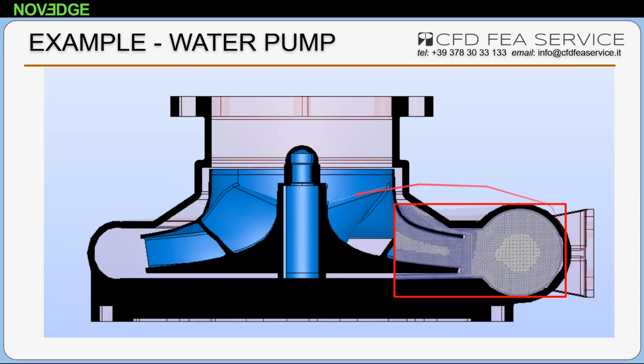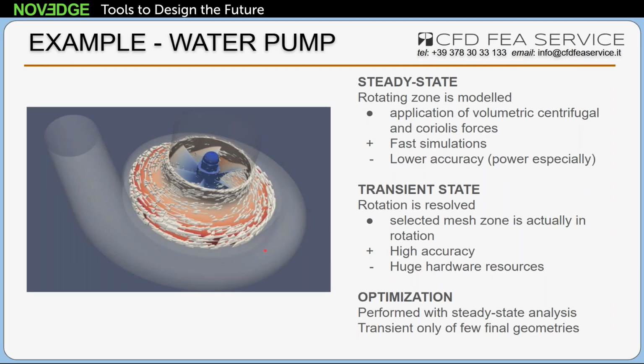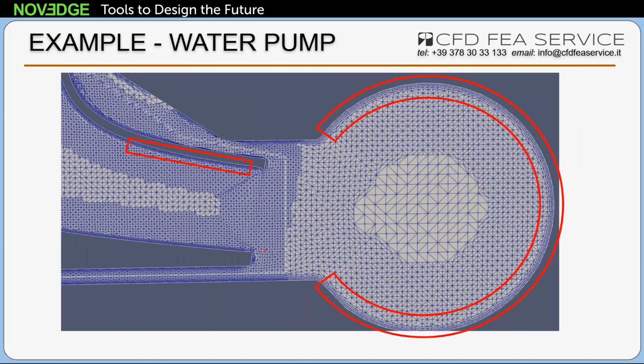Well, obviously, OpenFOAM can handle the mesh generation. I don't want to get into the details, but the mesh is composed of an inflation layer. There's many things to say. The inflation layer is these extrusion cells from the wall, which is super important in terms of accuracy of shear stress calculations.